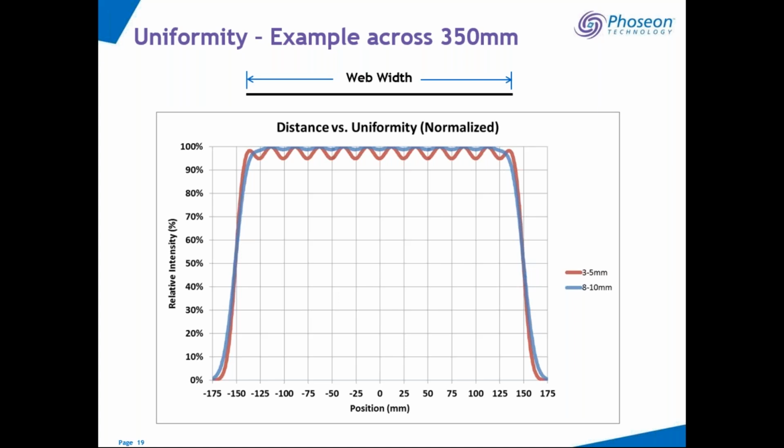And so there is this little wave that happens as you go across these LEDs, and the companies that can tighten that up and stay well above 90% are the ones that can provide a really nice uniform output curing solution, so that when you look at your print jobs moving forward, across the substrate there are not areas that are streaking, but fully cured across that capability.